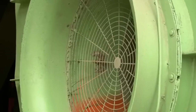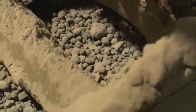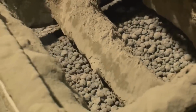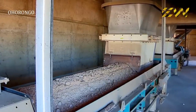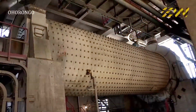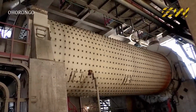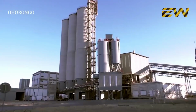The hot clinker spills from the lower end of the kiln into a clinker cooler. Cooling the clinker prevents undesirable crystal formations while preserving clinker quality. The cooled clinker moves to the cement mill, where gypsum and supplementary materials like slag, fly ash, or limestone are added. This mixture passes through a final grinding stage to achieve the fine, powdery finished cement. The gypsum controls the setting time of the cement.